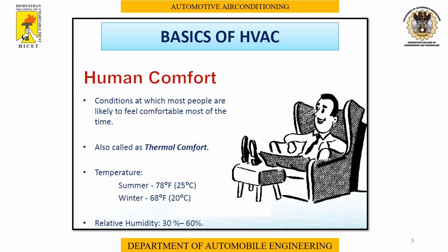In summer we have to maintain 25 degrees centigrade, which is 78 degrees Fahrenheit. At the same time, in winter the room temperature is maintained at 20 degrees centigrade. Another important thing is humidity. The relative humidity of 30 to 60 percent must be maintained in that particular room or cabin, whatever it may be.